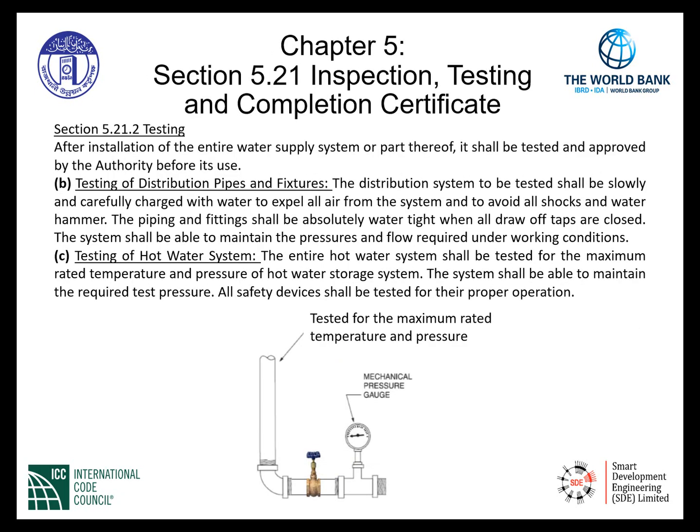Section 5.21.2 references testing. After installation of the entire water supply system or part thereof, it shall be tested and approved by the authority before its use. Item B specifically indicates testing of distribution pipes and fixtures. The distribution system to be tested shall be slowly and carefully charged with water to expel all air from the system and to avoid all shocks and water hammer.